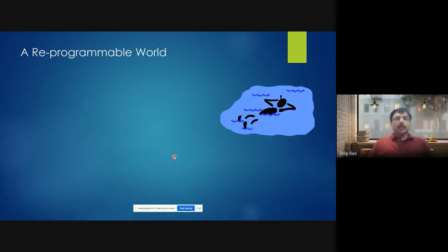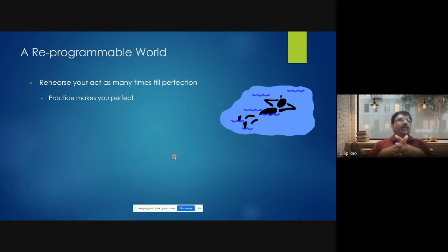So talking about the reprogrammable world, let us see what are the advantages that reprogrammable hardware brings to us. Reprogrammability basically means that the functionality is not hard coded. You're not limited to the functionality that is written and fabricated, but it is actually a fabricated IC whose functionality is open. It's a set of open unconnected gates. The functionality is decided in the field. This is the advantage or the luxury that programmable devices are bringing to us.